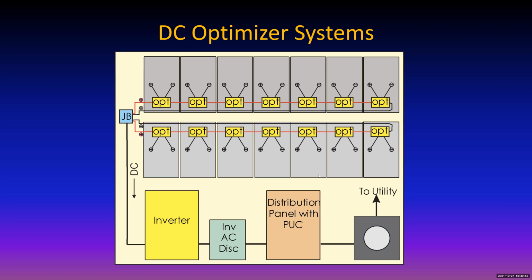And so let's see, Don, what do we got here? Does each cell have internal protection and alarm monitoring? Each module. Modules have internal bypass diodes such that it partially mitigates a shading issue even with a single module. And there are other modules where they have half cells, which are effectively 2 modules in parallel in one enclosure.